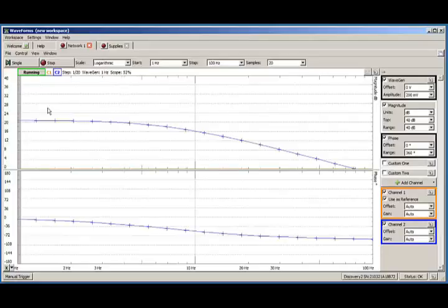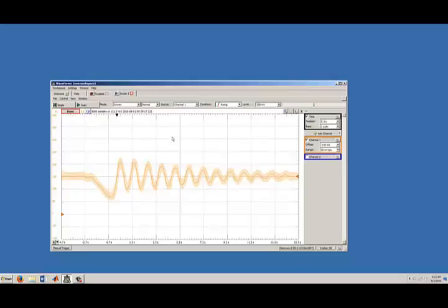Okay, there we go. I've got a DC gain of about 21 decibels. 20 dB would be 20 times the log 10 of 10, so I've got just about my gain of 10. The corner frequency is where the gain is down by 3 decibels. So here at about 17 is where my corner frequency would be. It's looking like it's about 7 or 8 hertz, which is good. So it looks like my filter's doing what it's supposed to do. Now I've got my filter implemented.